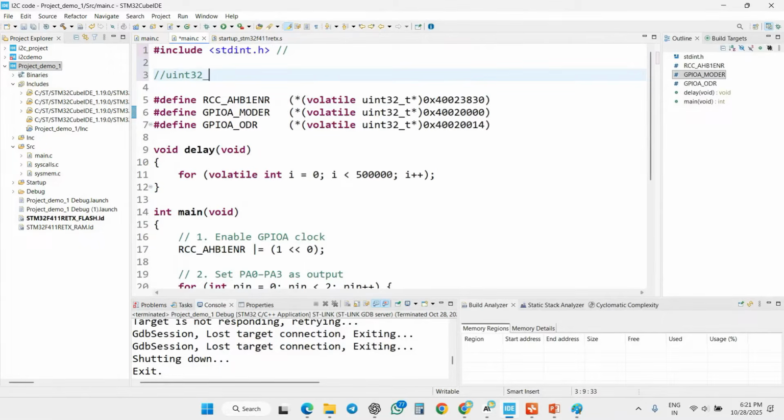If you're writing code with unsigned 32-bit, because in normal C programming you write the code in the form of integer, int, it is easy. If you are developing software, they won't consider the size and all. But if you are writing code for your microcontroller, we need to be concerned about the size. We know the size of an integer is 4 bytes.